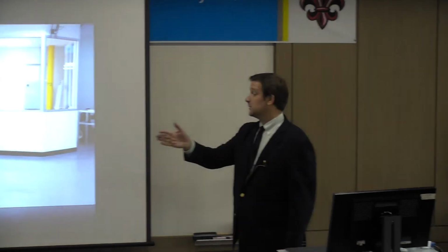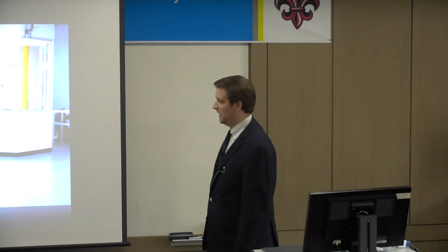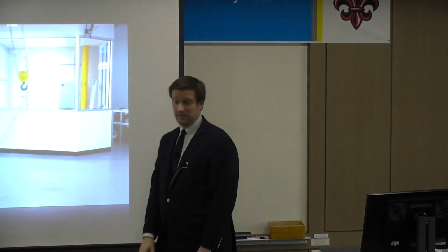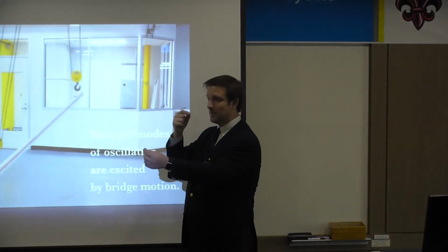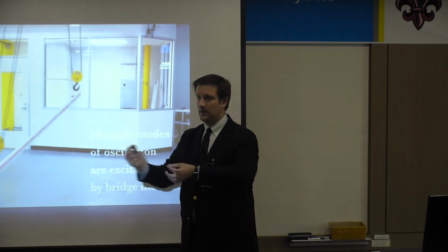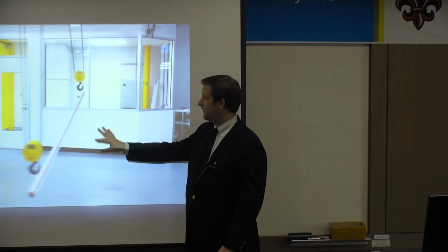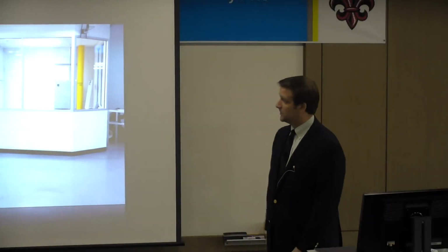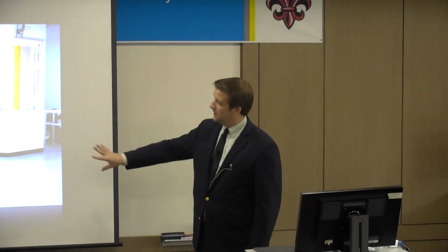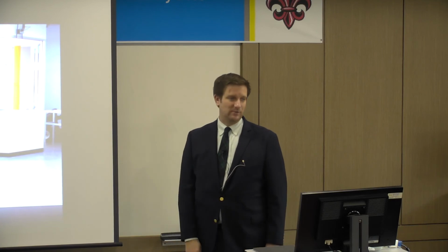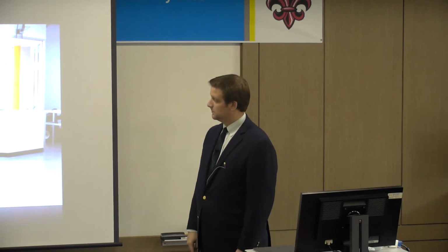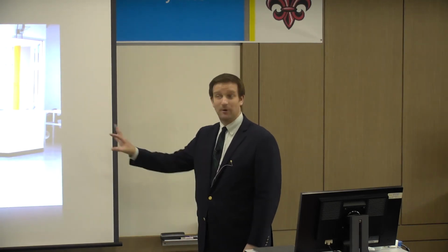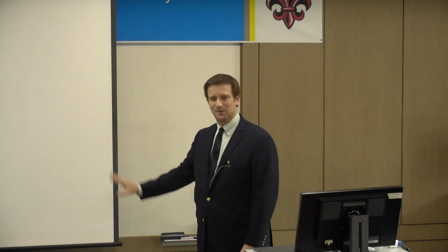However, if we move in the other direction, in the bridge direction we would say, I actually get 3 modes of oscillation. So I have the 2 cables and then this guy oscillating that way. And I know those 3 modes of oscillation now. What I can do is take those 3, design an input shaper for that, and move it this way and still get really, really low vibration. And you see not 0, but almost 0.